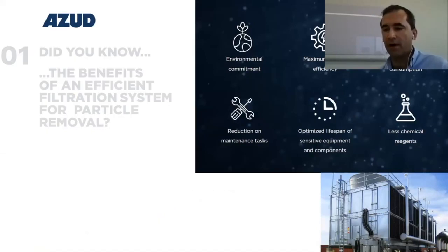This is a very common application, and it is very easy to explain, as these suspended solids are consuming part of the biocidal or sodium hypochlorite. So by removing them, the residual disinfectant will last longer, and also the dosing will decrease, so you will have savings in chemical consumption. Of course, other benefits are implied, as the environmental impact by having less blowdown, less water consumption, and all the maintenance tasks, replacement of spare parts, consumables, etc.